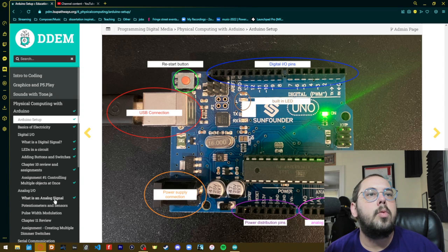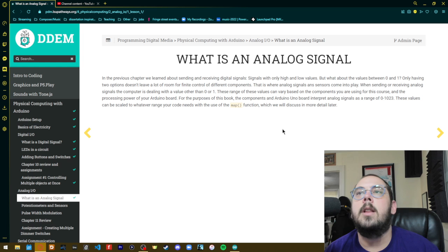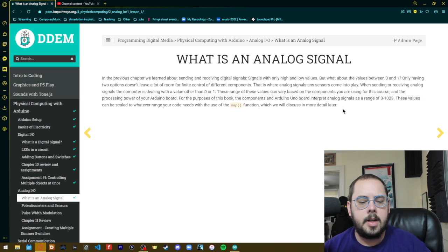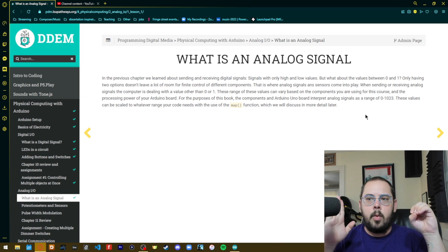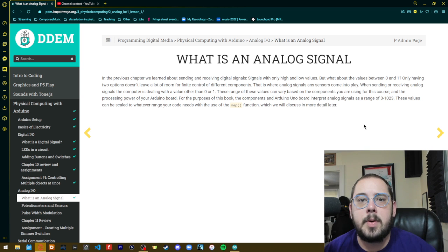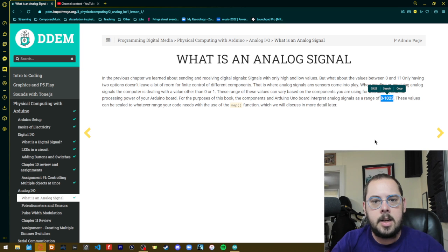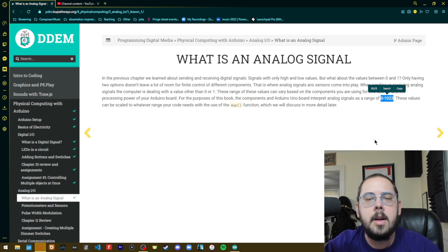Hopping into Arduino Analog again real quick. The way it works is that the analog side of the board can detect variations in amounts of electricity between 0 and 100%. In this particular case, because of the bit depth, we're not working in audio, but basically the computing power of the Arduino Uno, we have a total of 1,024 different differentiations of that signal.